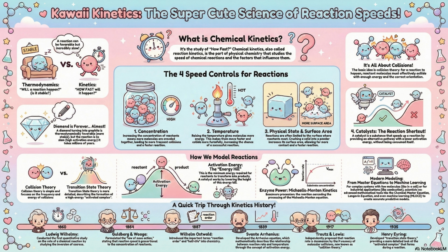Can you give a specific example of that compromise, where a rate constant had to be physically dishonest to make the model work? A great one is the virtual reaction rate for CH3 plus O2. The optimization showed that to match the ignition delay time at 40 atmospheres, that virtual rate constant had to be increased by almost 150% compared to the value that worked best at 10 atmospheres. So you're forcing this one fake reaction to do the work of hundreds of real ones that you deleted. That's it exactly. You're tuning the simplified network to compensate for all the missing physics.